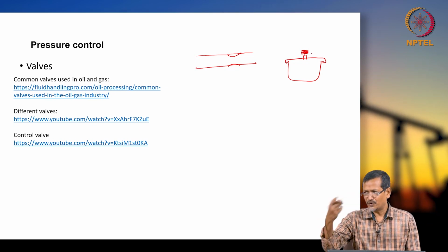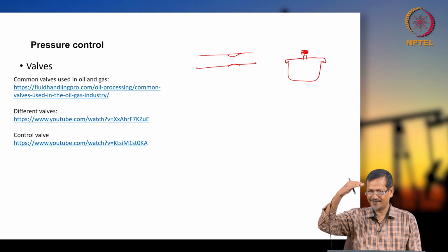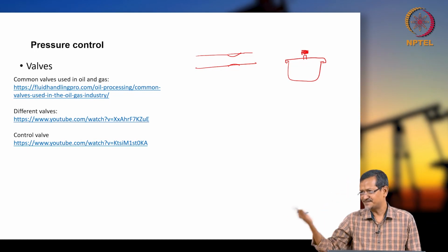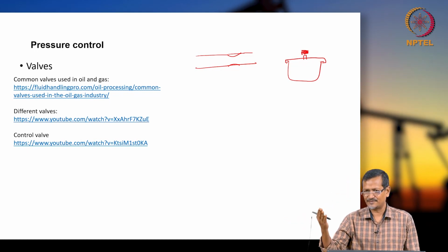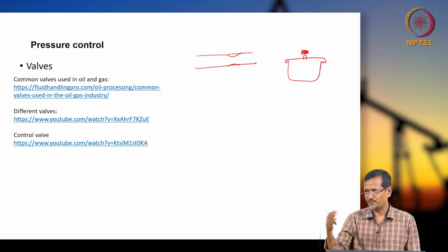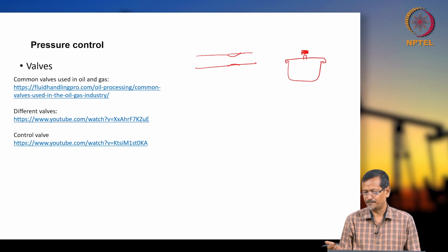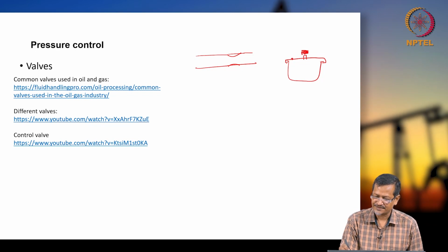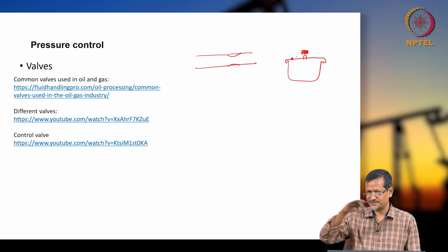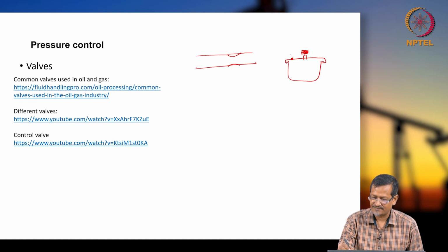If pressure goes beyond 2 bar, the valve will open and release the steam. If you do not release the steam, what will happen? It can burst. If pressure is very high, then it can be an accident. There will be a safety valve also here somewhere. If you look at the lid of this pressure cooker vessel, there will be a safety valve.